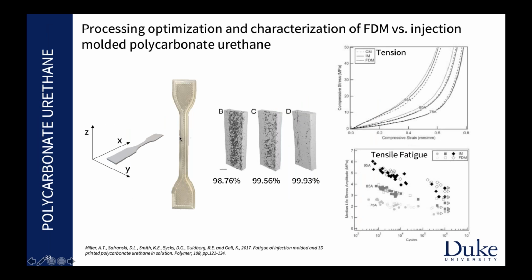We do a lot of studies in that, trying to understand, all right, when you do fused deposition modeling, how much porosity do you get? You're not trying to get porosity here. And so these are examples of something, and a small amount of porosity can actually have a big impact on how it looks and what it does. So that's just a couple percent porosity in B, and you see you actually end up having a lot of pores that can have a big impact on the strength.